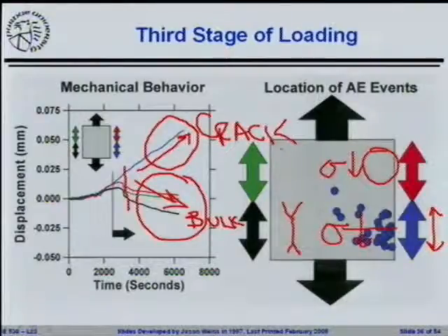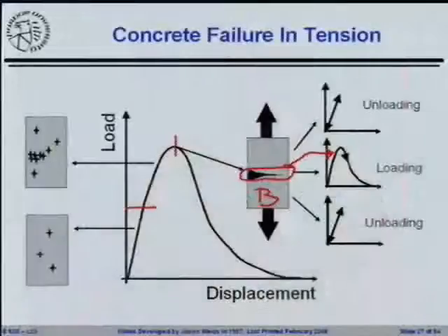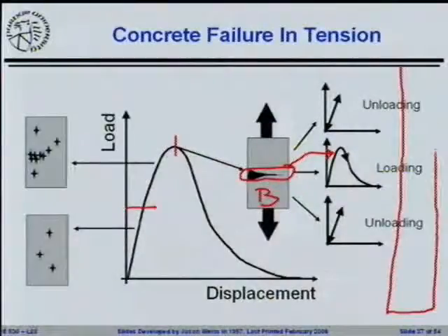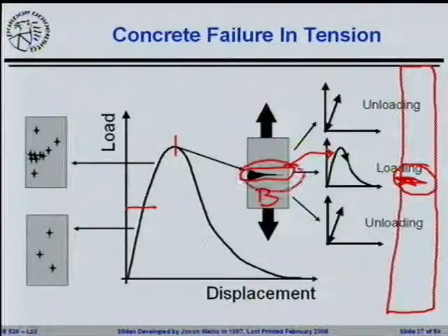The real issue is that damage is localized to one region of the sample. So if this specimen were twice as big or 3 times as big, right? I make a bigger specimen over here. The localized region, the cracked region, stays exactly the same. The energy that's lost from this part of the sample is the same as the energy that's lost here. I'm not talking about making it big just in one direction; we could scale it in different directions.